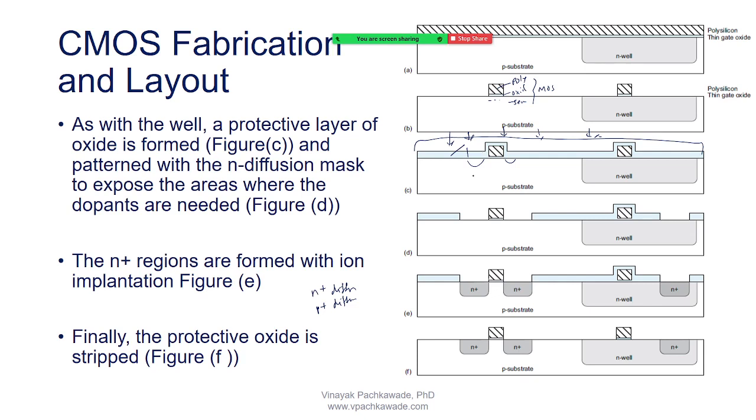Light rays pass through the mask where the mask were put, and light rays were blocked on the remaining portion by the photoresist that we had grown. So light rays pass through the mask and the photoresist was exposed, and that portion of the photoresist got melted or softened and other photoresist remain intact.